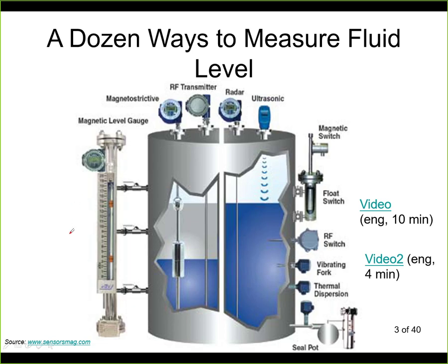And here on the left you have a very simple example of how you may do it as well. You can imagine that we can have a float that is placed near the tank. It is connected with connecting pipes like this, and the liquid level is the same in the tank and in this tube. So this will be the very first example that we will be talking about. And we can see visually directly what is the liquid level in the tank.